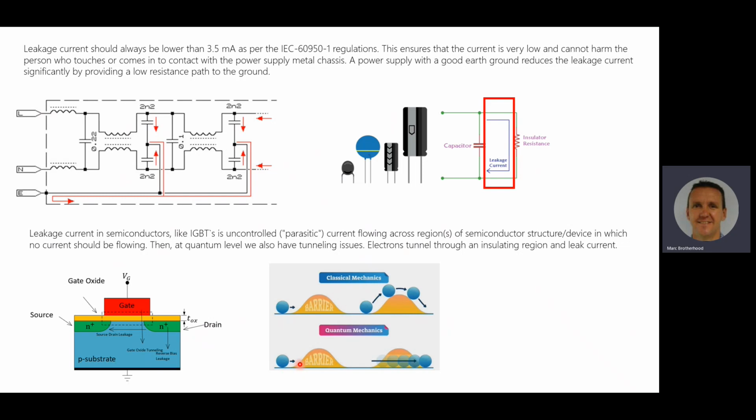It can reach a very minute insulation barrier, and the laws of quantum mechanics say that particles also behave as waves. So it's a wave-particle duality effect, and this particle suddenly becomes a wave at quantum level, and waves tunnel through barriers. So therefore you're carrying a charge. It doesn't even need to roll over. It tunnels through as a wave function. And as it tunnels through, it's got charge and it develops leakage current.